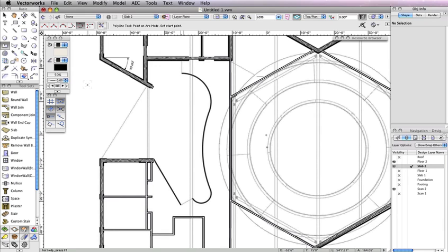Take a look at this curve. You can see it's basically composed of 3 arcs. With the Polyline tool in this mode, you can draw all 3 composed arcs in one shot, instead of having to trace each arc separately and then snapping to the endpoints and composing them.